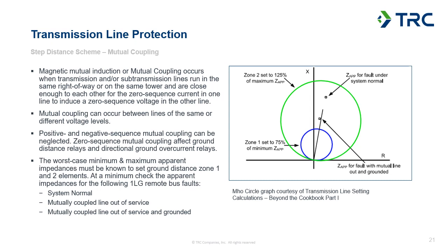So Aspen can do a good job of evaluating and showing us how those relays would respond, and we would simulate dozens or even hundreds of faults within the surrounding transmission system to make sure that for all cases where we had an in-section fault, the relay is operating the way we expected it to, and for any faults outside of the line, that we're not tripping instantaneously on that zone 1 element.